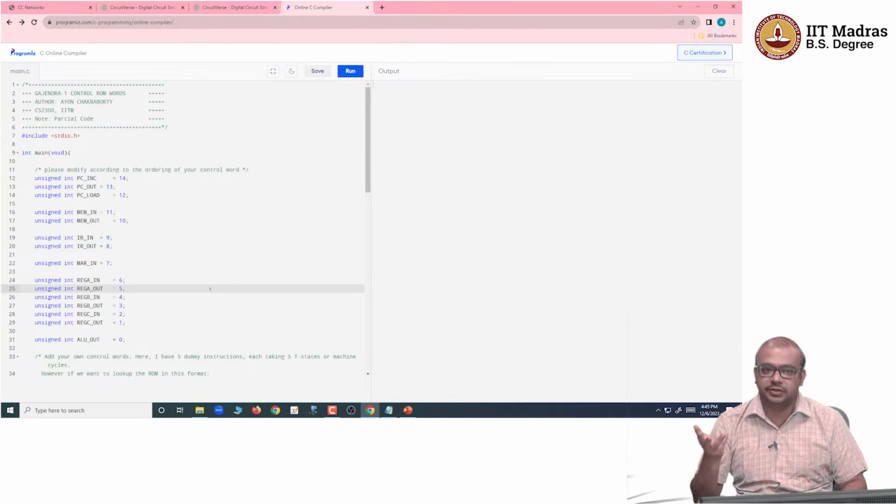If you ask how many bits at the minimum are required for the control lines, if you have 8 registers, without any optimization the answer would be 8 plus 8 equal to 16. For 8 registers you want to set ones or zeros for selecting the inputs, and for the output only 1 bit has to be on, but without any optimization you are wasting 8 bits.